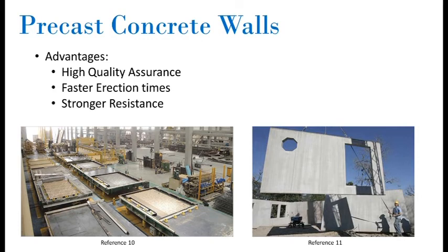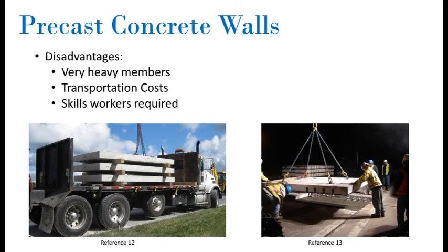Using precast walls can result in faster erection times on-site. The walls are reinforced with steel rods, providing stronger resistance to wind and earthquake loads. However, precast concrete walls are very heavy members and need to be transported on-site for erection.